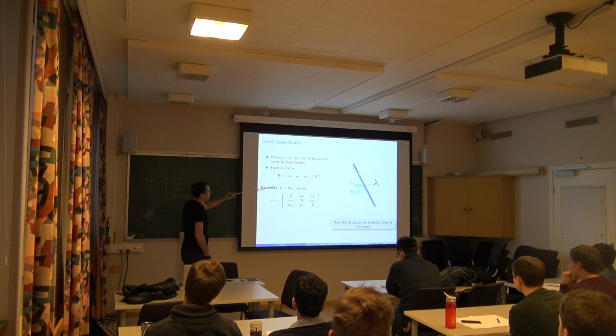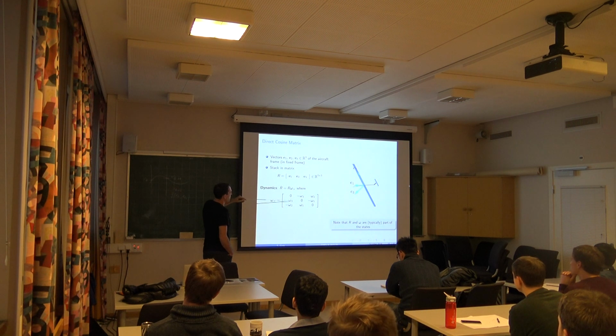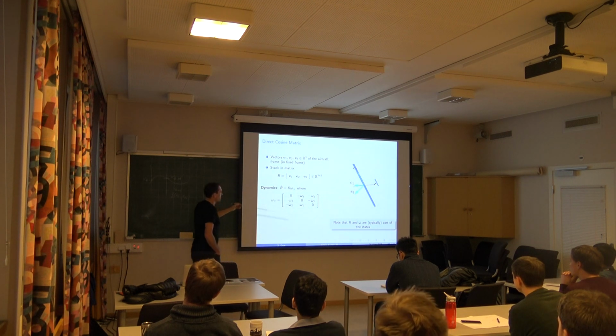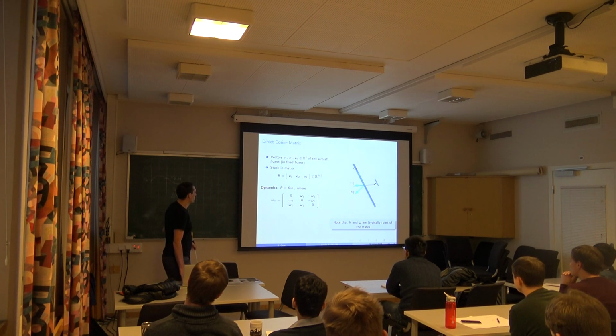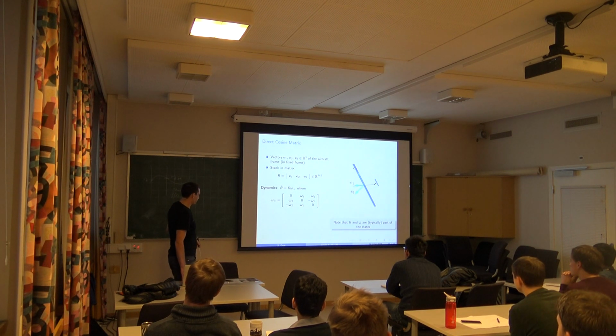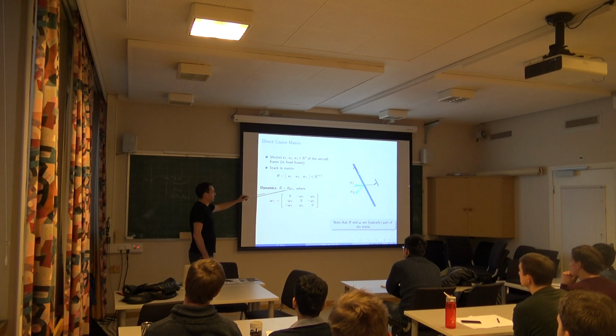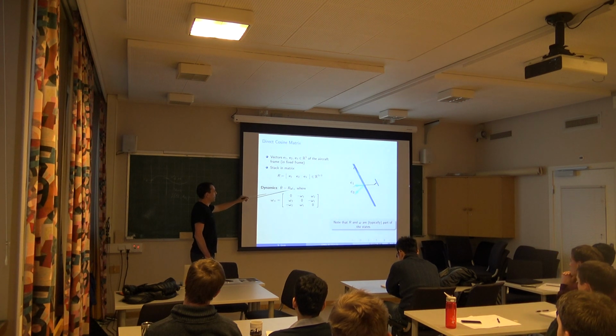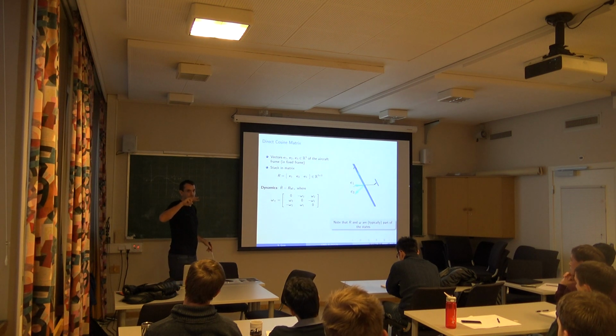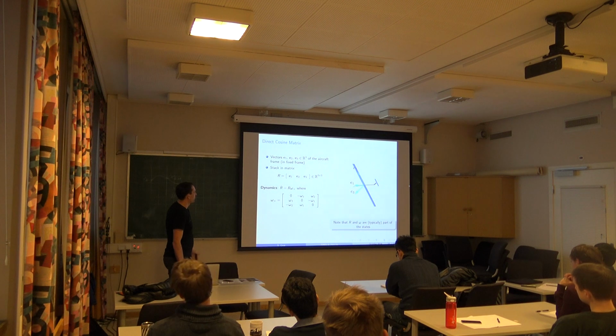And then the dynamics become very simple, because R dot is given by R times this matrix made of the rotation velocities around these 3 axes, and it's a skew symmetric matrix. So it's a very specific structure. But here the dynamics are very simple. It's bilinear, right? If R is part of your states and omega is part of your states, you're basically just having multiplication between states, as opposed to, for example, having lots of sines and cosines if you have Euler angles. And quaternions are also a little bit more nonlinear than that.